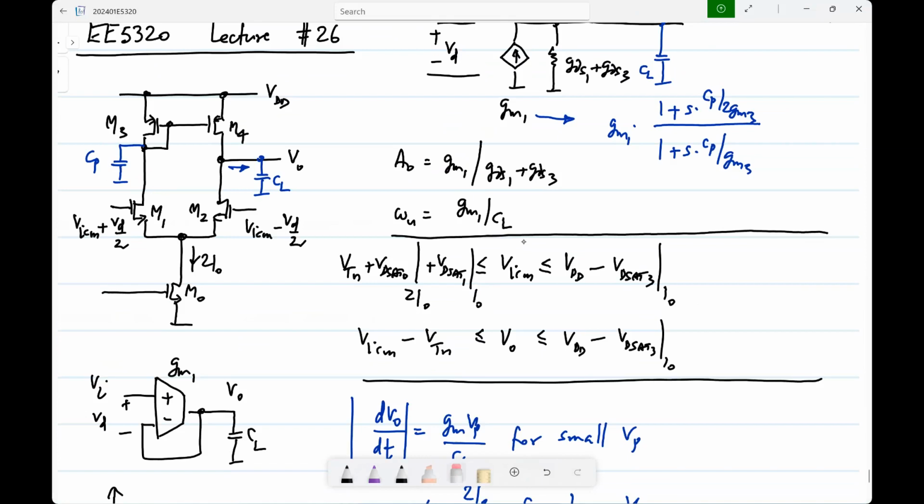What is that? No. The assumption is always that the operating point is set correctly, right? Otherwise, the circuit won't work. The operating point is set correctly, and after that, you apply signals to it. I mean, for small signals, you never consider any change in operating point, right? By definition, the incremental small signal picture is that you have the picture around the operating point. That's what you use. Okay. But yeah, I mean, if you swing the common mode substantially, there is no cutoff, right? It will only be that this will go into the triode region. With common mode swings, nothing will cut off. Okay.